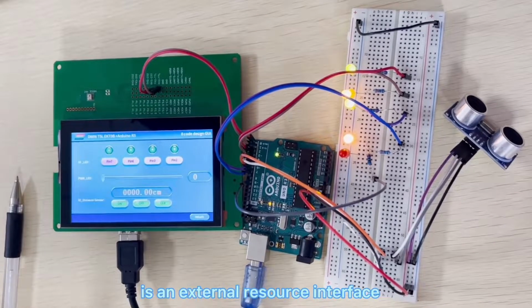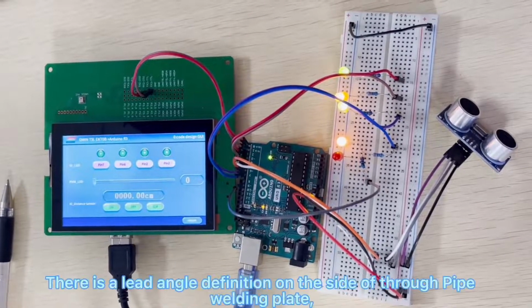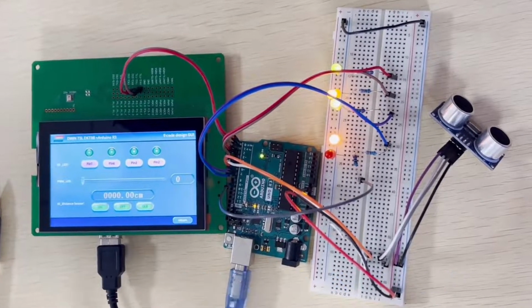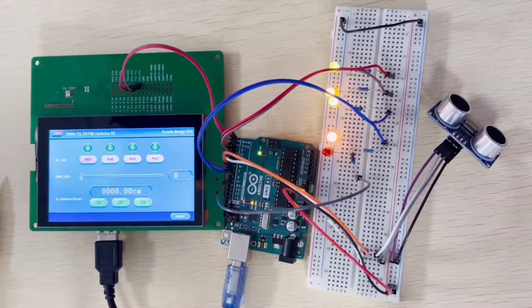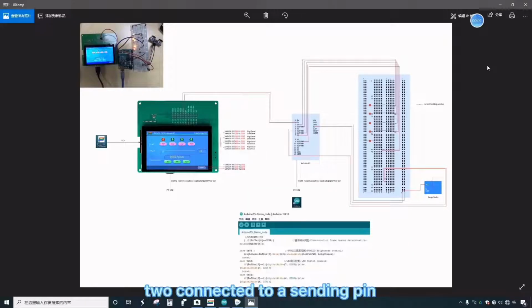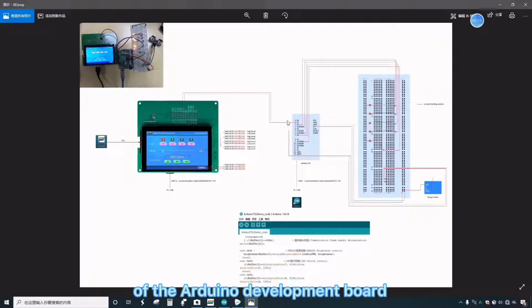The development board is an external resource interface derived from the T5L chip. There is a lead pin definition on the side of the through-hole pad. The pin function can be used as needed. Here is serial port 2, connected to the sending and receiving pins of the development board. The pins are TTL level. It is connected from this communication interface to the transceiver pins of the Arduino development board. Here, the transceiver pins are cross-connected: T is connected to R and R is connected to T.